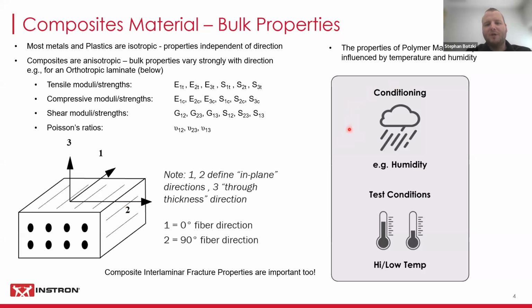So they do take up humidity. And it also depends if you're thinking about an airplane operating up at 30,000 feet, they will be in different temperatures than down on the ground, for example, right? So if you're testing your composites, you've got to make sure that you also simulate the different conditions that your material, your end application, needs to operate in. So you've got to have them conditioned in a humidity chamber, something like that, where they get saturated with the right amount of humidity. And then you also need to simulate the test temperature that your material is supposed to operate in.